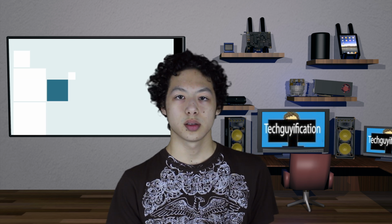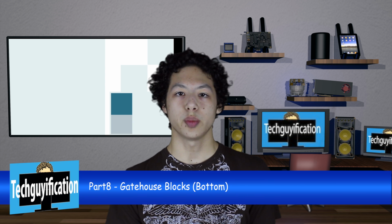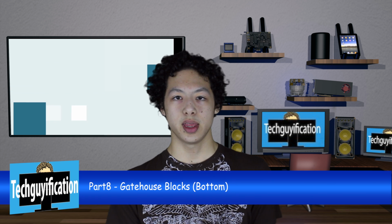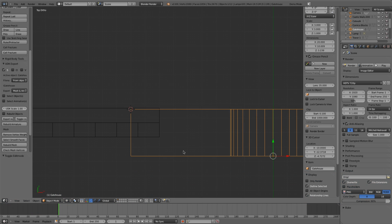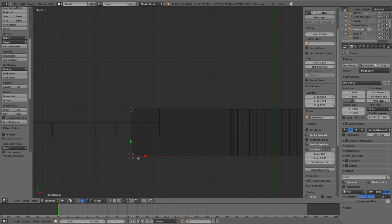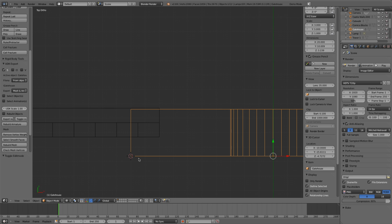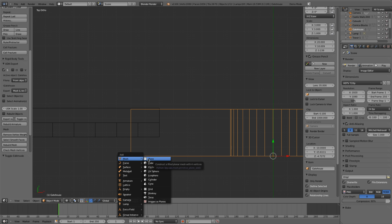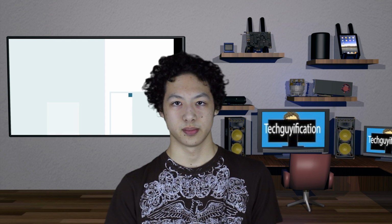So now we're going to add some blocks to the bottom of the gatehouse. So go back into front view by hitting numpad 1, and then go into edit mode for the gatehouse, then select the bottom left hand vertex, and then Shift S, cursor to selection. Next, go to top view by hitting numpad 7 on the keyboard, tab out of edit mode, and then press Shift A and add a new plane.